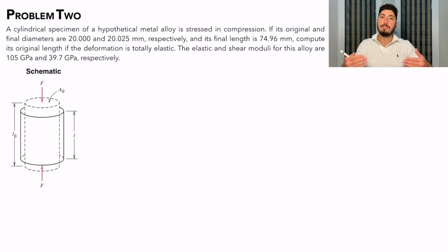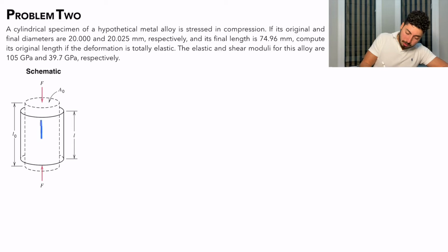So this is again a very fundamental problem. And what this problem is trying to teach us to do is relate the strain in one direction to the strain in another. So what we should first do is to simplify the problem. So let's develop a coordinate system or an axis that we can use. So going to our schematic here, we will define the stress and strain in our transverse direction as our x direction, and our strain in the longitudinal direction as our z direction.